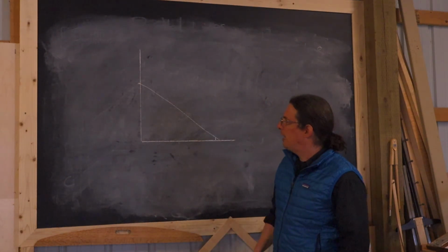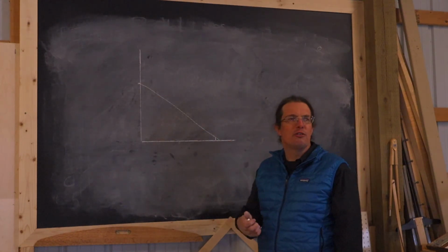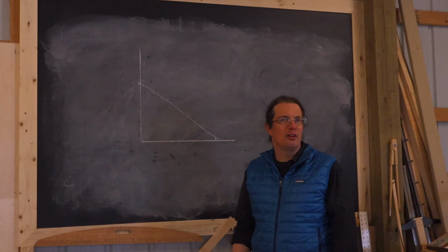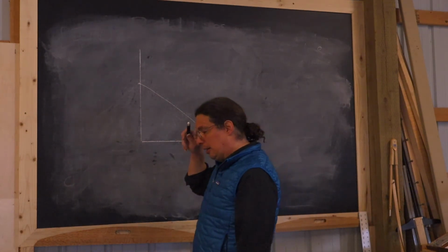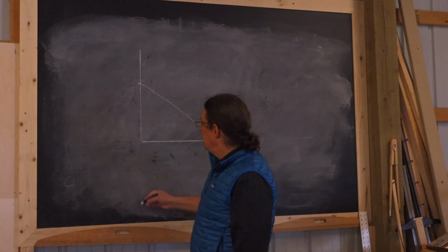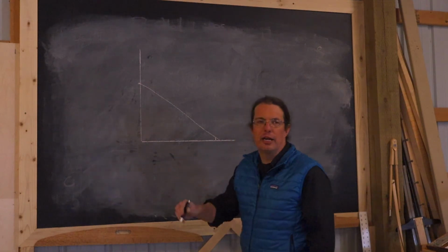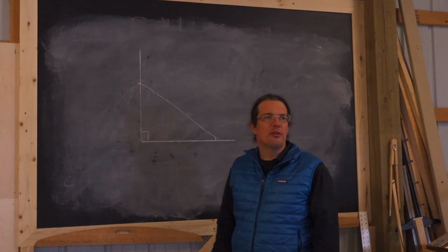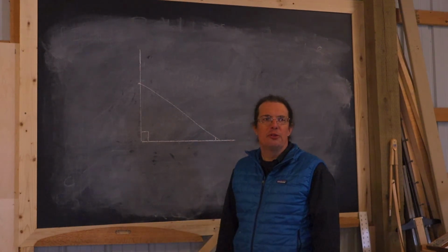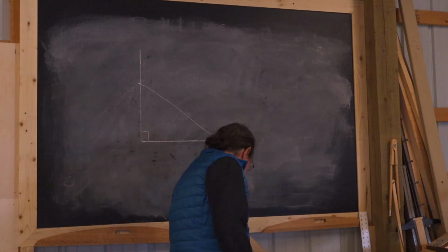triangle that looks like that, and put a stake in the ground there, there, and there as you're stretching the 3 tape measures together. It takes some helpers and it takes some coordination, but once you've put a stake here, here, and here in the ground, then you've ensured that this angle right here is going to be right. And then you can build the rest of your foundation up off of that good first start.